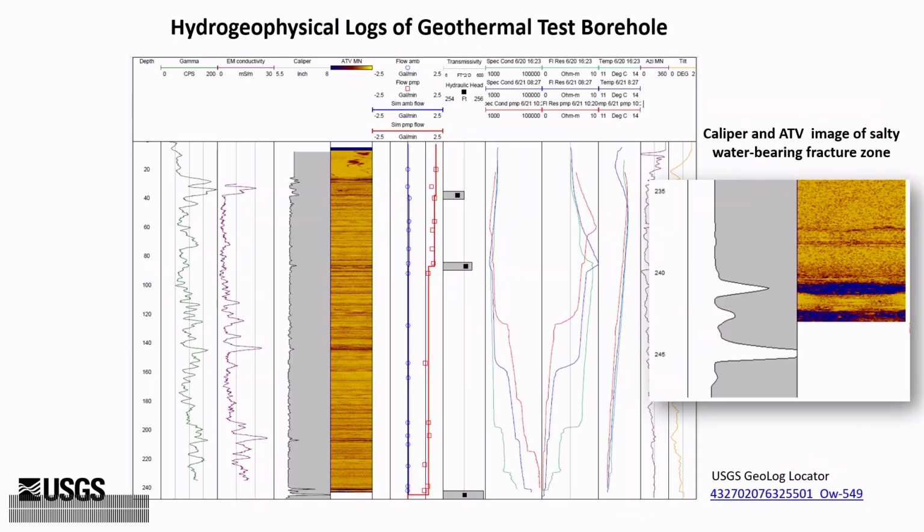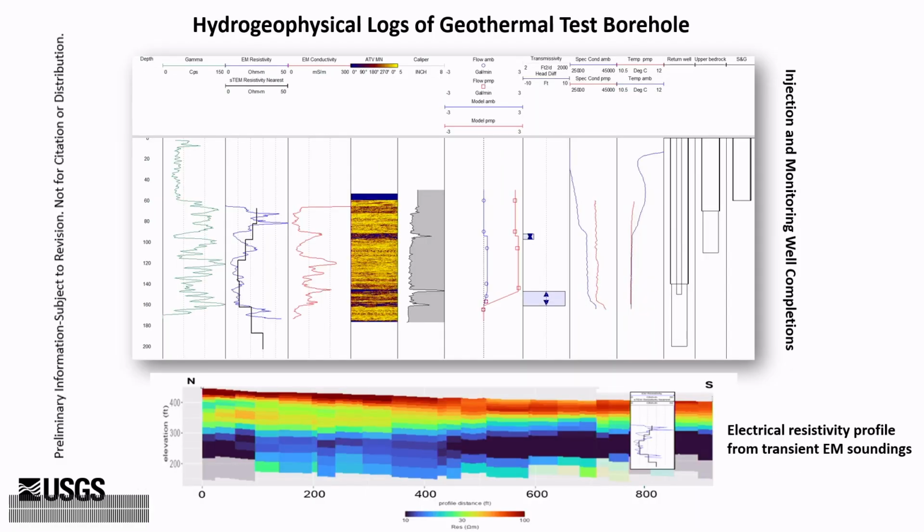model. We've logged two geothermal bores in the interior lowlands, and two of those hit large quantity of salty water at relatively shallow depth. This well is at SUNY Oswego and hit a couple hundred gallons per minute of very salty water, and you can see from the acoustic televiewer, it's a bedding plane. Here's the second one that hit salty water. This was at Lyons in Wayne County.